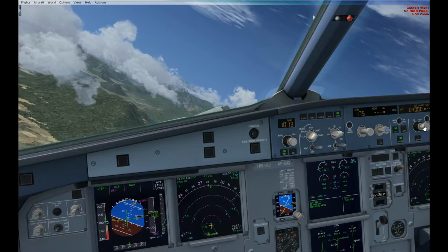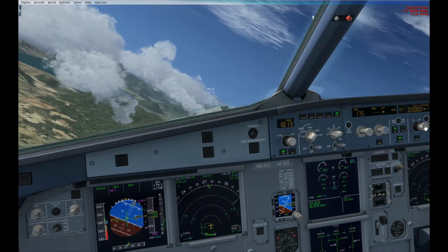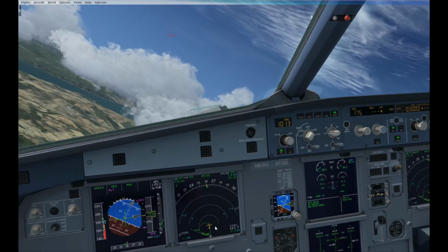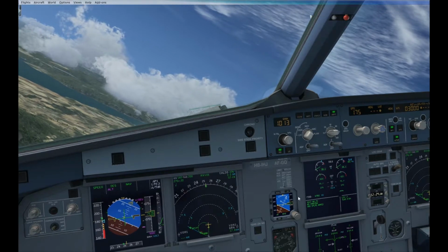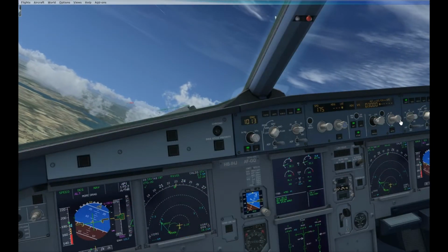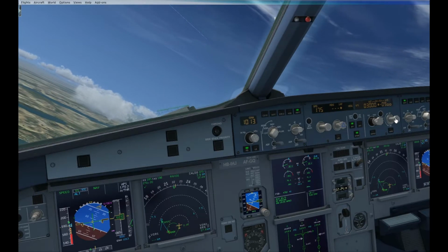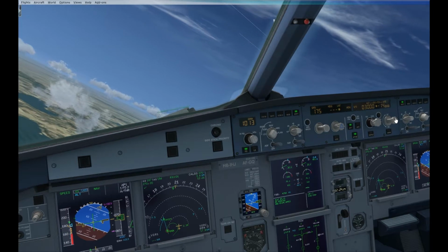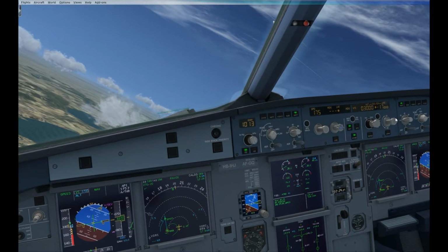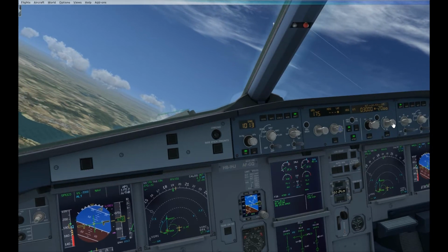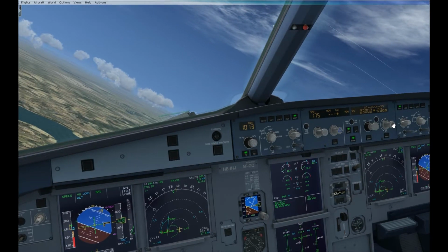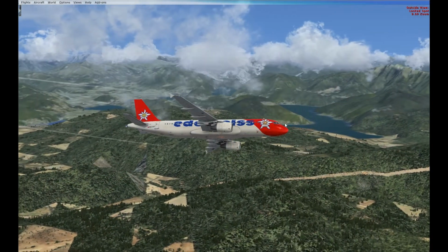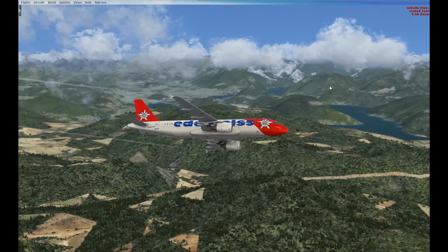I also wish to reduce my altitude to 3,000 feet. Aircraft now making this final turn and reducing. I can increase my rate of descent by right-clicking the button on the right and inputting the rate of descent that I wish to accomplish. I'm going to put in 2,000 feet per minute descent. My required airport is over here.